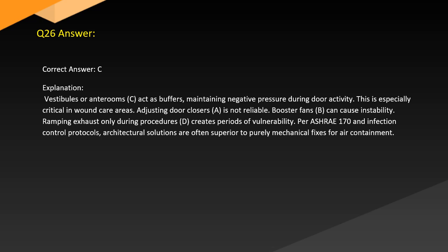Adjusting door closers (A) is not reliable. Booster fans (B) can cause instability. Ramping exhaust only during procedures (D) creates periods of vulnerability. Per ASHRAE 170 and infection control protocols, architectural solutions are superior to purely mechanical fixes for air containment.